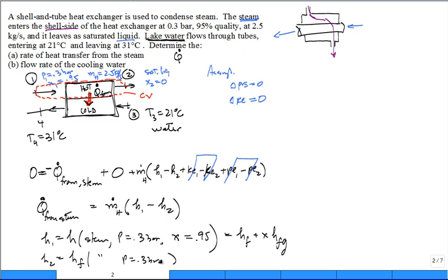Did they ever really tell me exactly that the pressure on the inlet is equal to the pressure at the outlet of the hot fluid? No, then just say that the pressure at 2 is equal to pressure at 1. I have to assume it. But it seems reasonable. A lot of times unless there's a restriction, the flow just flows freely through our pipes and there's negligible pressure drop. Now, when you have a pump, the purpose of the pump is to create a huge pressure gain. When there's a turbine, there's a huge pressure change across the turbine. But for things like heat exchangers, the purpose is to promote heat transfer, not change the pressure of the fluids.